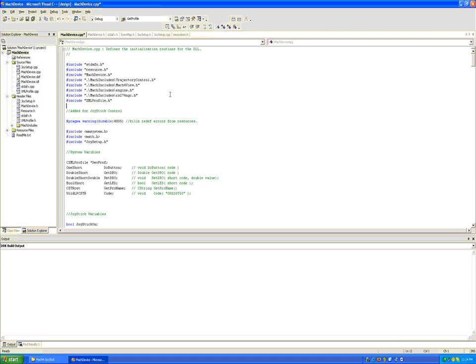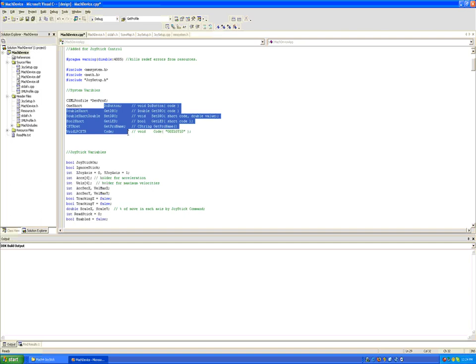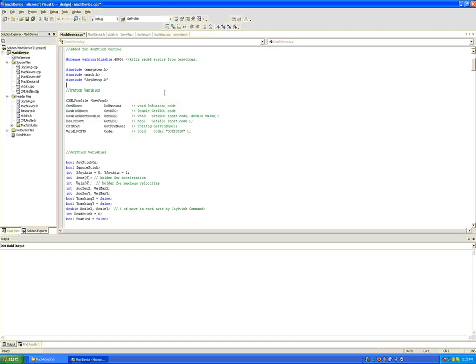Ask questions, yell at me when you have a specific question on a variable or where to find a variable. Most of the variables are stored in the places that I've given you access to. If you wish to get DRO values and so on, use these calls: do button, get DRO, set DRO, get LED, and get code to send code directly to be executed by Mach 3. All of those functions will work within the context of Mach 3, and it's pretty much invisible to the system.